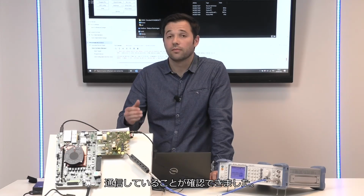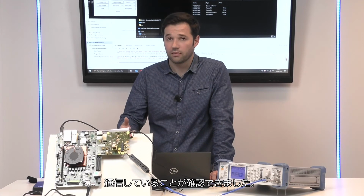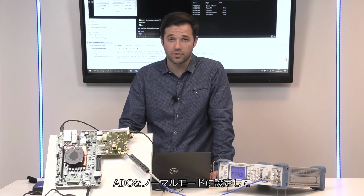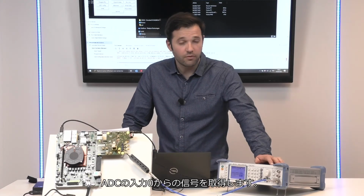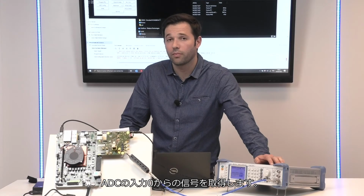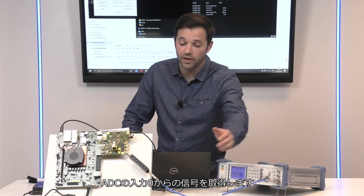Now we know that the communication is working properly, we can configure the ADC in normal mode to start a signal acquisition. I'm generating with the signal generator a continuous waveform at 4.5 GHz on the ADC input 0.